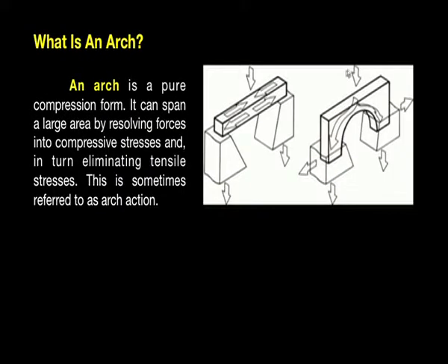If you look at a normal compressive member, which we saw in a previous episode, a post and lintel fashion, you can see how the load transfers in a post. On the top surface of the post, there is a compressive stress acting on the post, whereas on the bottom surface of the post, there is always a tensile stress acting on it. A tensile stress is nothing but a pulling force, whereas a compressive stress is a pushing force. In arches, the beauty of an arch is that it is entirely of a compressive stress nature. There are absolutely no tensile stresses involved.